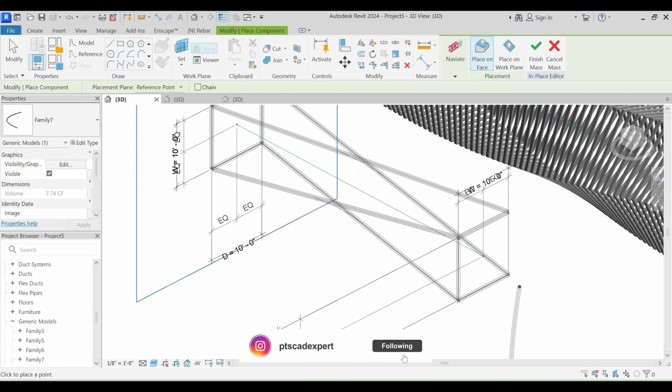Okay, this particular parameter has been associated, giving it a rotation angle. So if I just go to the family types and change this to 60, then you have a different result. And you can have n permutations and combinations of the same design.